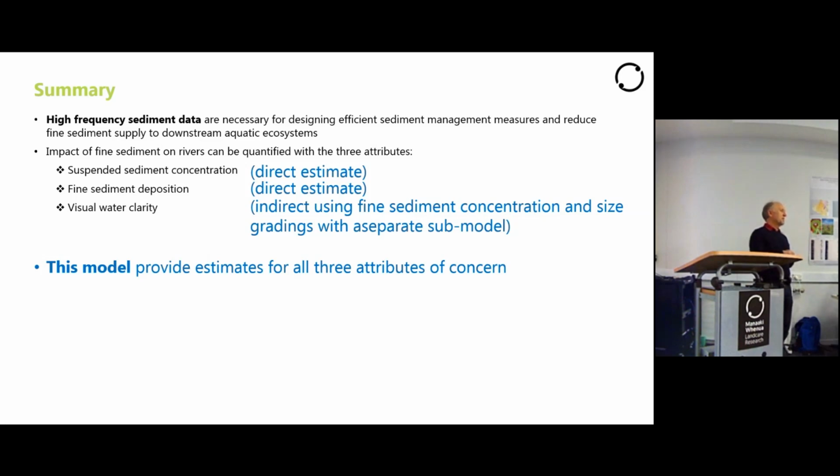So you might make a reduction of 50% of the sediment load, but it's assuming that the particle size is the same at median flow. We don't know whether that's true. But that's the reason why we have to get this temporal model to look at that. And that would be one of the first things we check. We run some scenarios with soil conservation scenarios and just see what happens to the sediment concentration at median flow.